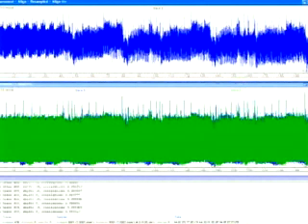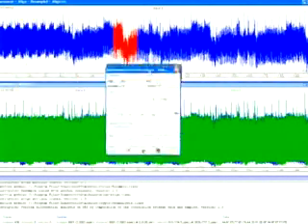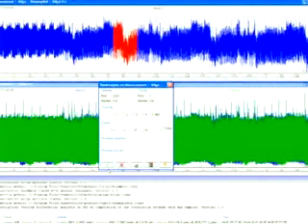Now we are going to select the area where we know the S-box is being calculated, and we use the routines for the correlation part. In this case, we're using the Hamming weight of the output of the S-box. Because all the transistors are switching at the same time, and the output is used as a nibble or something in a byte, we get a Hamming weight effect: it matters how many bits are switched to 1 and 0. And that's what we use to correlate.